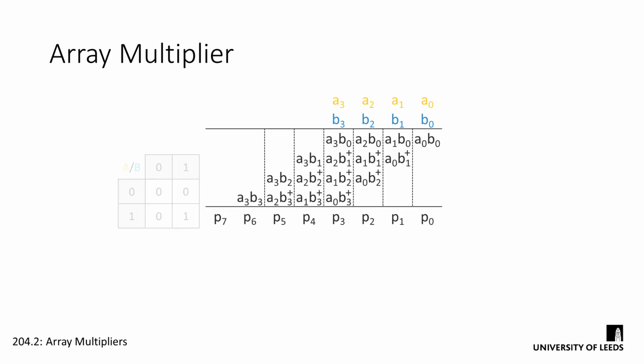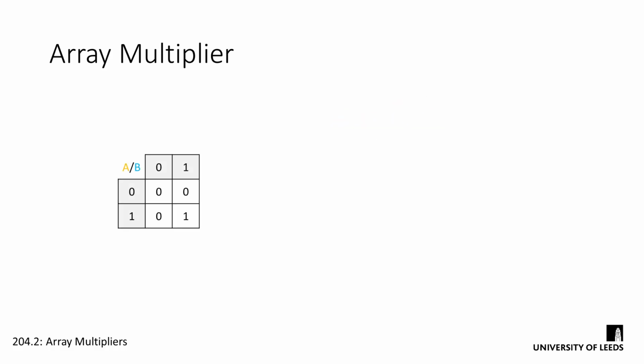If we take a look at the truth table for binary multiplication again, we can very quickly see that multiplying two single bits together gives exactly the same result as just ANDing them. So in fact, we can conduct multiplication in hardware asynchronously. We just need a lot of AND gates to generate each bit of the partial products, and then wire them through adders to generate the final result.